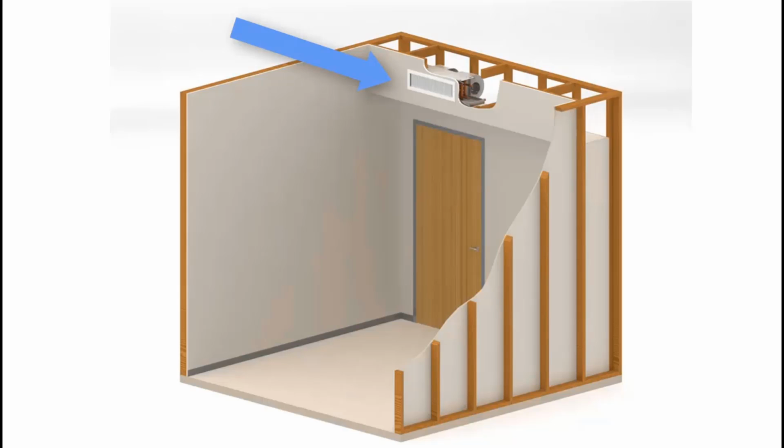Room air is returned to the unit through the bottom of the fur down just in front of the entrance door. The air then passes up into the blower section of the fan coil and then is sent through the water coils horizontally through the supply grill and into the occupied space. This is a good installation as it uses little ductwork and does not consume floor space.